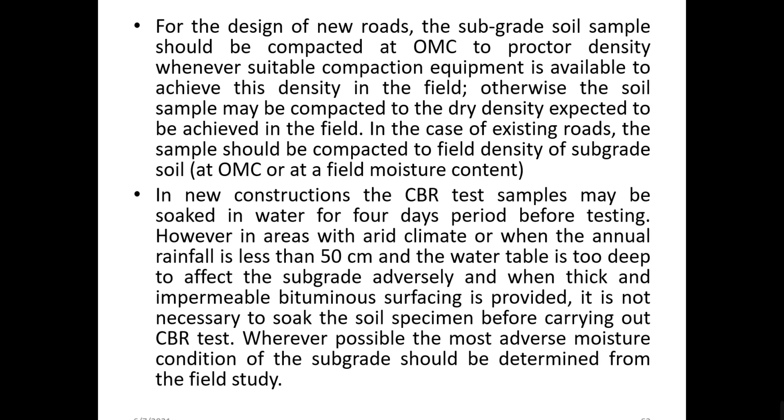So first of all, we have to mix the suitable water content, which is going to be called the optimum moisture content, into the soil, thoroughly mix that soil, and take that particular soil into the test specimen for testing, to obtain the result of CBR in terms of percentage. Okay, so that is what they had said.